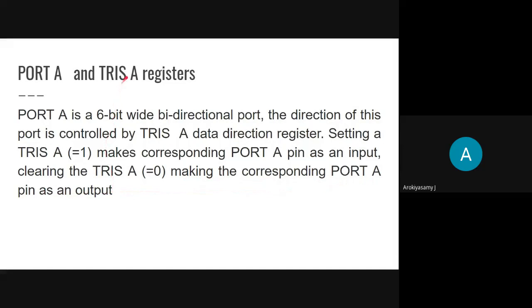So if you clear bit 0 of the TRISA register, then RA0, that is port A bit 0, will act as output.